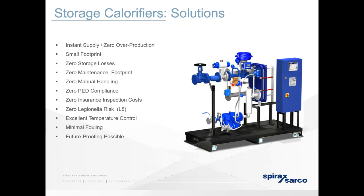There's no Pressure Equipment Directive, no PED, because there's no pressurized vessel. It doesn't need insurance costs. There's zero risk of Legionella because again there's no standing water. Good temperature control because it's on the line. Minimal fouling because the surface area of the unit is smaller, and it future-proofs because you can improve the equipment that's on it.